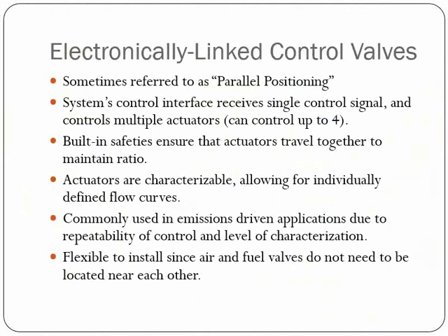Okay. All right, so moving on, we're starting to make a jump in the combustion technology. This is fairly new technology within the last 15 to 20 years. We're starting to undo the mechanical linkage and go with electronically linked control valves. Sometimes we refer to this as parallel positioning. This system has a central control interface.